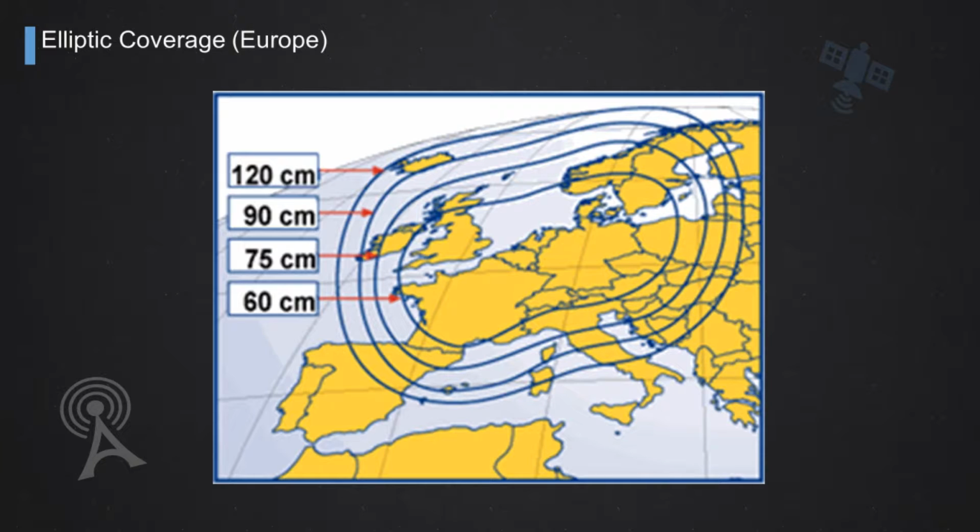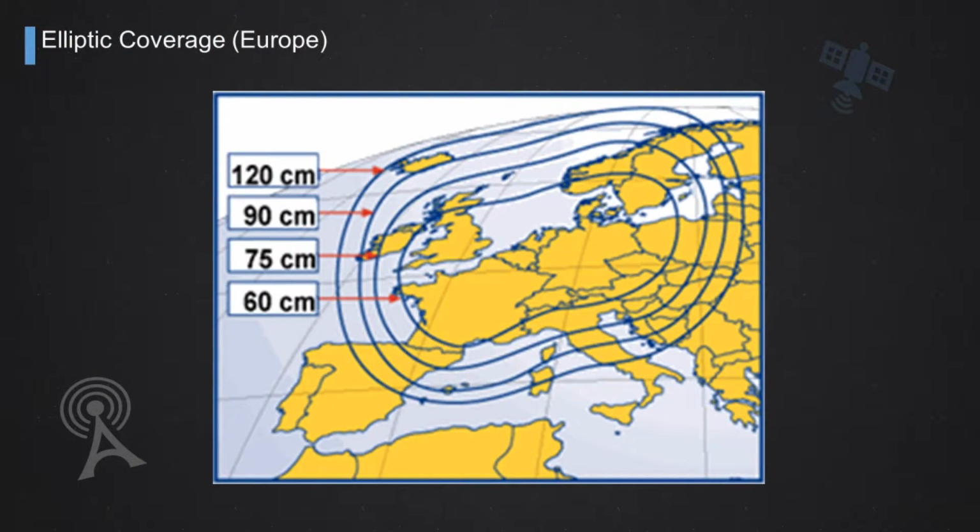Circular or elliptic are very similar. It depends on the symmetry of the aperture on board that is creating the beam. So the elliptic coverage is the simplest coverage I can think of to illuminate a certain area of the Earth that I want to serve with my communication link. It can be generated on board by an elliptic aperture, the ellipse being a general case for a spot beam, circular shape or elliptic shape. So in this case, the elliptic shape fits rather well.